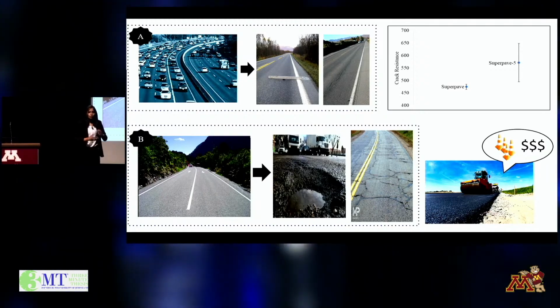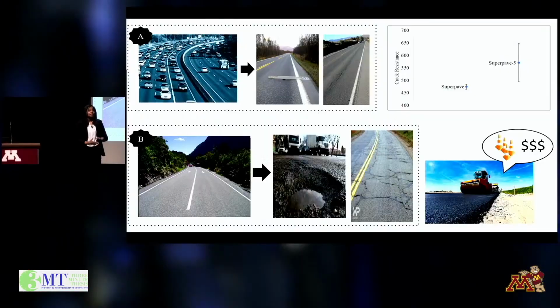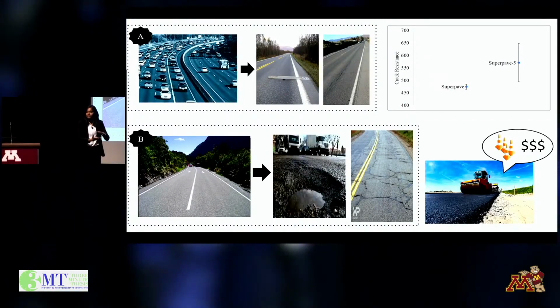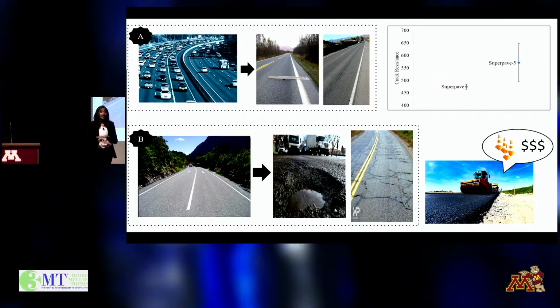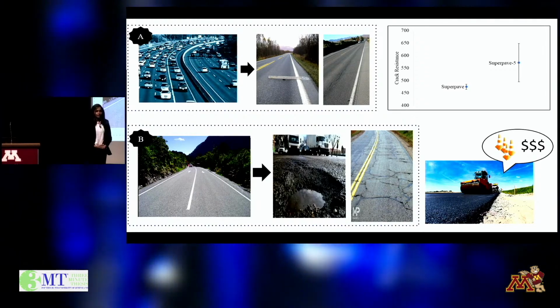But in case of low volume roads, if you are going to place an asphalt mixture with 7 to 8% air content on the field, is there enough load to cause the compression? No. So what happens is that the excess air content in the asphalt layer attracts moisture from outside and deteriorates the pavement, giving rise to potholes and temperature cracking.